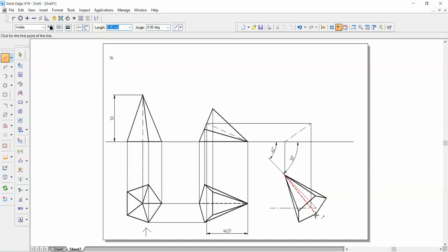I know that this particular thing is the corner, so it will rest on XY. These two lines are here. Okay. Project this. Another point will also rest on this one line. If you are getting this 90 degrees, then well and good here. If you are not getting it, just change the angle to 90, because sometimes the mouse may give you some problem. So the other two edges are there.